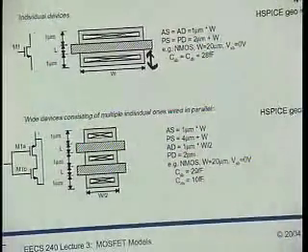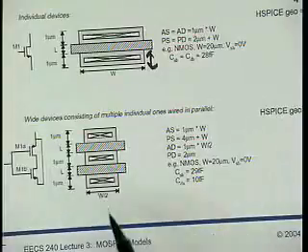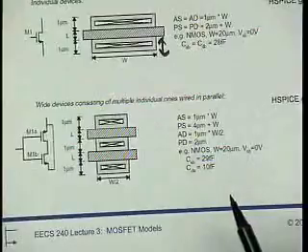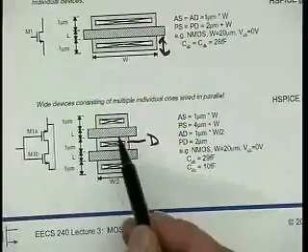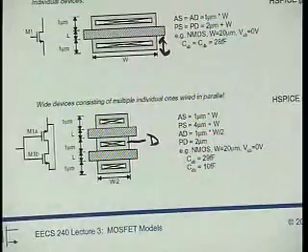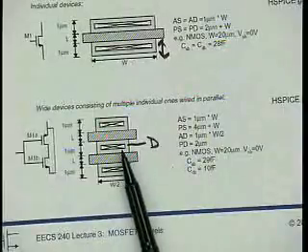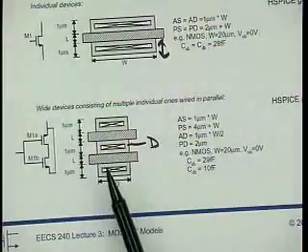We could have laid out this device also as two devices that we then wire in parallel. We just wire their gates together and their sources and their drains together, right? Then we get something like that. Now we can share one of the two terminals. This terminal we can call whatever we like. Here I would like to call it the drain terminal, because obviously this has less capacitance than these two junctions together, right? So now I found a way, and put the numbers here, to reduce the amount of capacitance by more than a factor of 2.